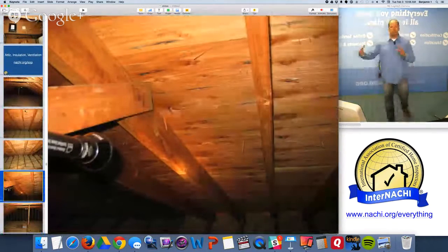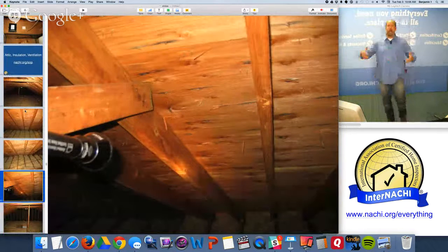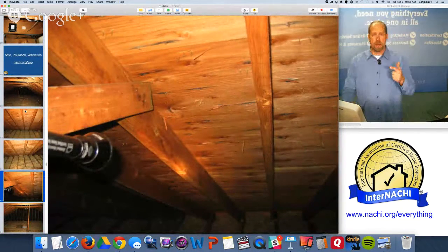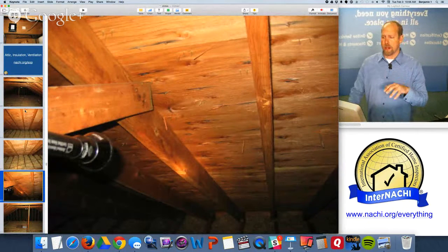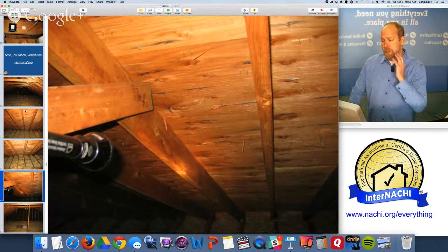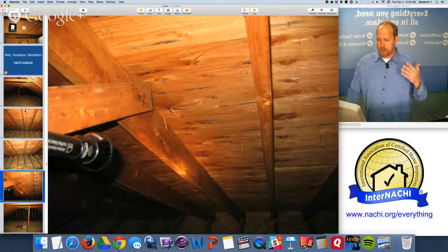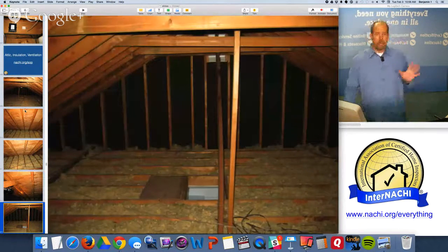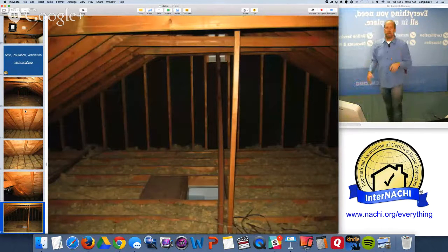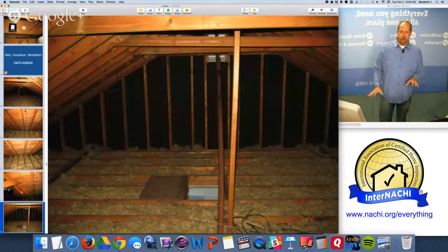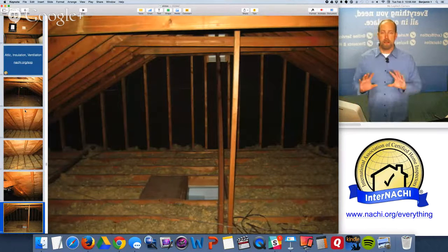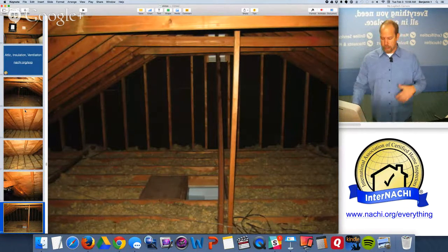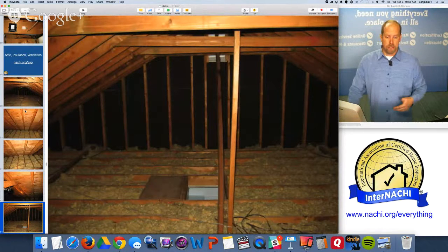We had all those roof problems on the outside, and now you have to remember that as you come into the other system. You want to take a look at the general structure of the roof, and look for water damage, water intrusion, signs of watermarks, and there are signs of water. I don't care if it's dry or wet. I'm going to call that out. I want to make sure my client knows that there's been something going on in the past that allowed water to intrude. And I recommend the seller comment upon this as well.